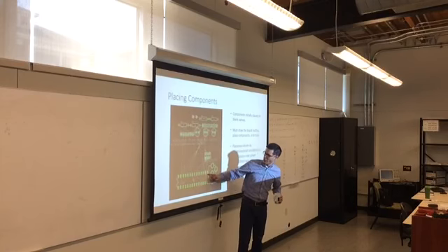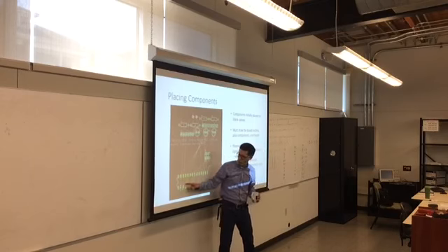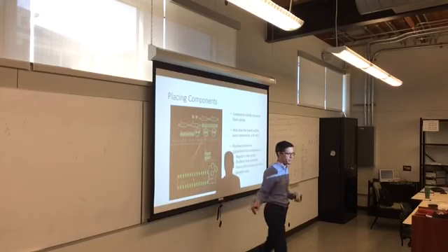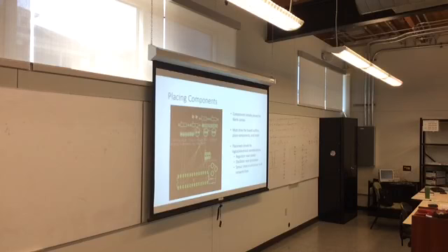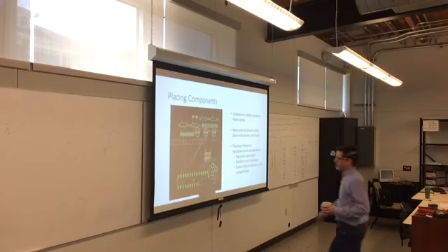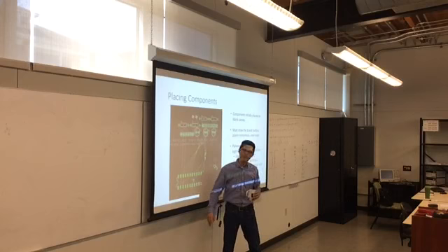One thing to note is where this green circle is, that means there's a drill hole. That means that there's a via or a hole through the board, and you don't want your wires to get super close to those holes because a drill is going to come through and bang out a hole in your chip. And if your wire's there and it cuts your trace, it doesn't care. So don't think that you can just naturally turn these wires around 180 and run them through the chip.